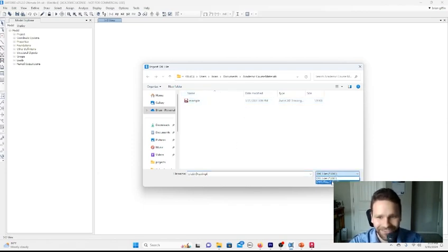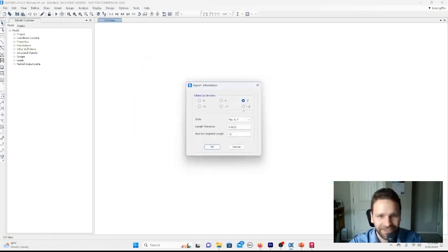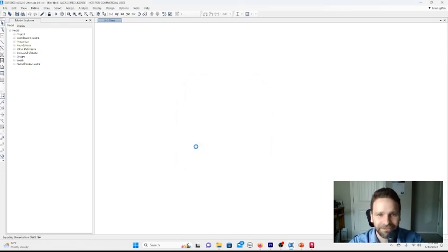I actually had to go to the drop down, switch to DWG files, and then actually import the AutoCAD.dwg format. Selecting your file and then specifying a few parameters, like what's the global up direction in your SAP2000 model compared to how it's defined in your DWG file. Set what the units are. These units should be consistent with whatever you defined in your AutoCAD file relative to whatever dimensions you specified, and then you can maybe leave these parameters alone. Just set them as their default values.